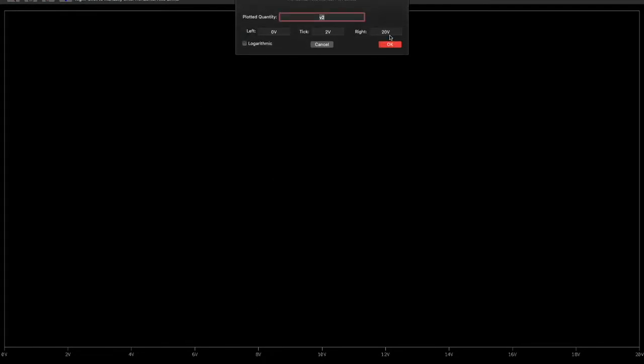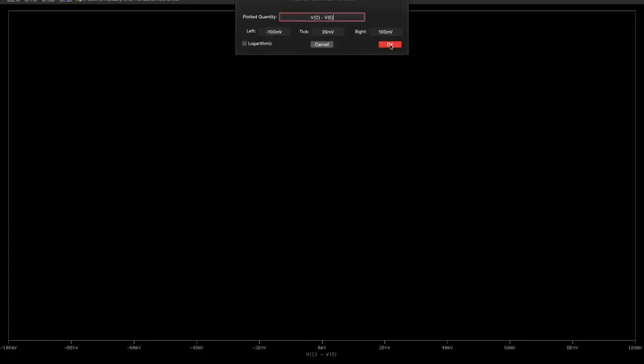All right, so we have to change the axis on the bottom here. So typically when you're doing BJT IV curves, you plot the voltage at the collector, at least for an NPN, minus the voltage at the emitter. So this would just be reversed if you're doing it for a PNP. Okay, so we'll go from 0 to, let's go up to 2 volts.